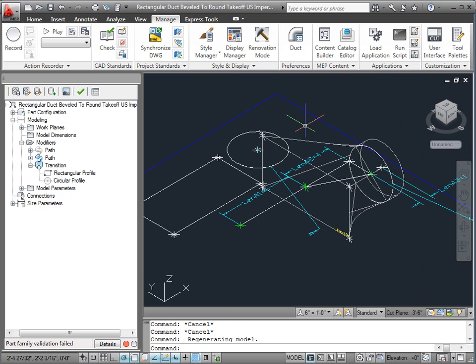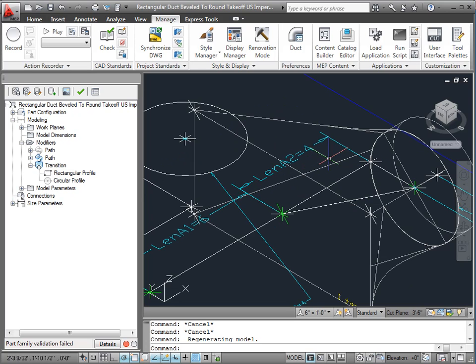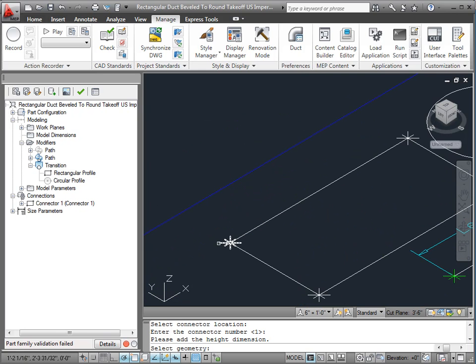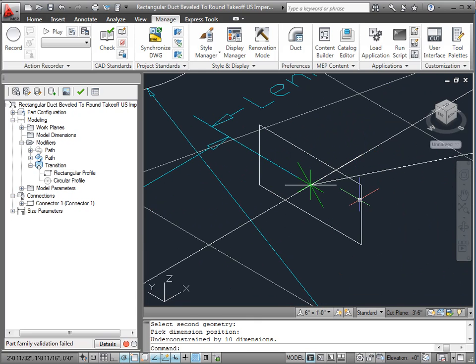When placing these connectors, if we're looking straight down on it in plan view, it becomes hard to specify what direction the connector should face. So let's switch to a different perspective and say Add Connection. And there it notices it wants to grab it and enter connection number 1. Select Geometry. Okay. It still wants to point the wrong way.